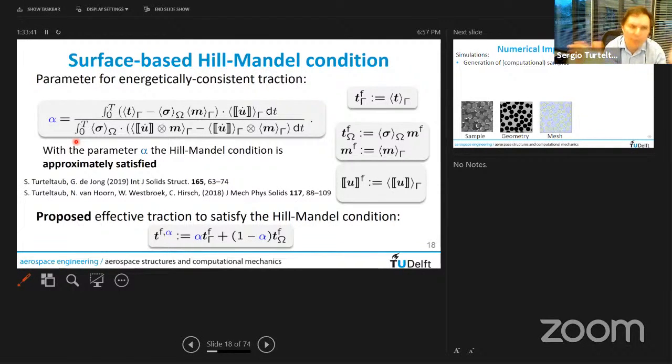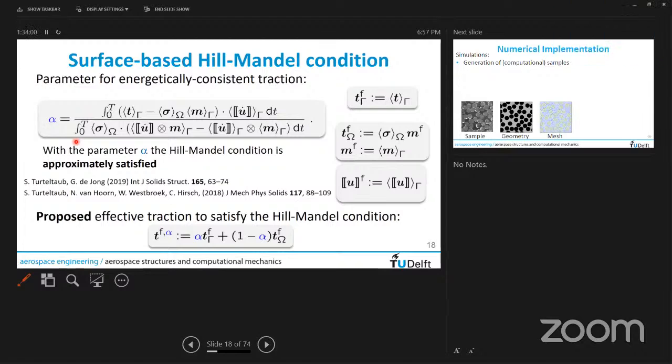So there I will agree with you that this is not something that I would use blindly everywhere. You really need to look at what is the cohesive zone length and what is the physical size of a ply. And if they start to collide, then this doesn't work. Correct. Right. Okay, I have one last question, if you allow.